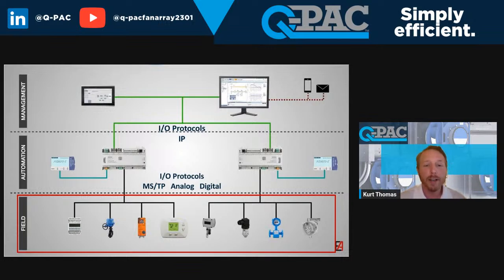We're a little bit more complicated than your pressure transducer, but we do communicate through MSTP and give you a lot of great data. And then there's the automation side. So all of your devices run back to the automation side. That's where the logic is done. That's where the controls contractor will make all of your set points and all of your sequences.